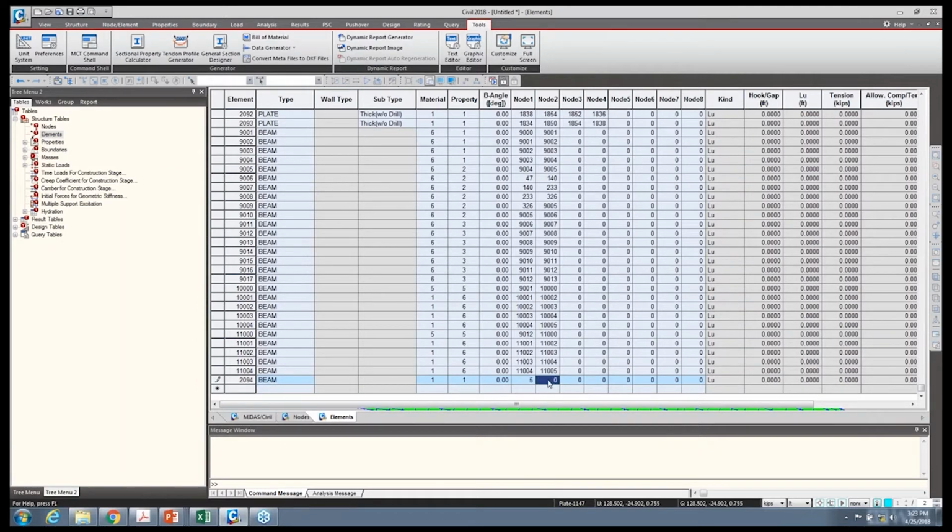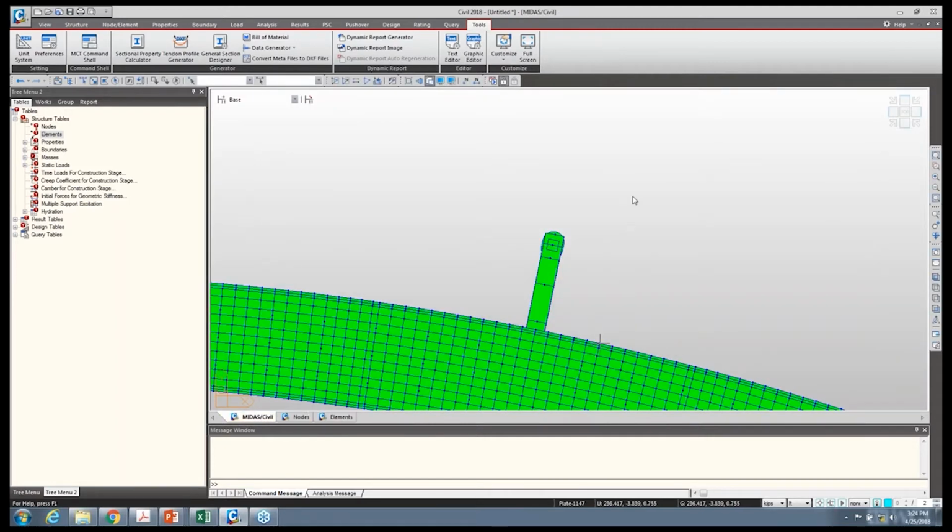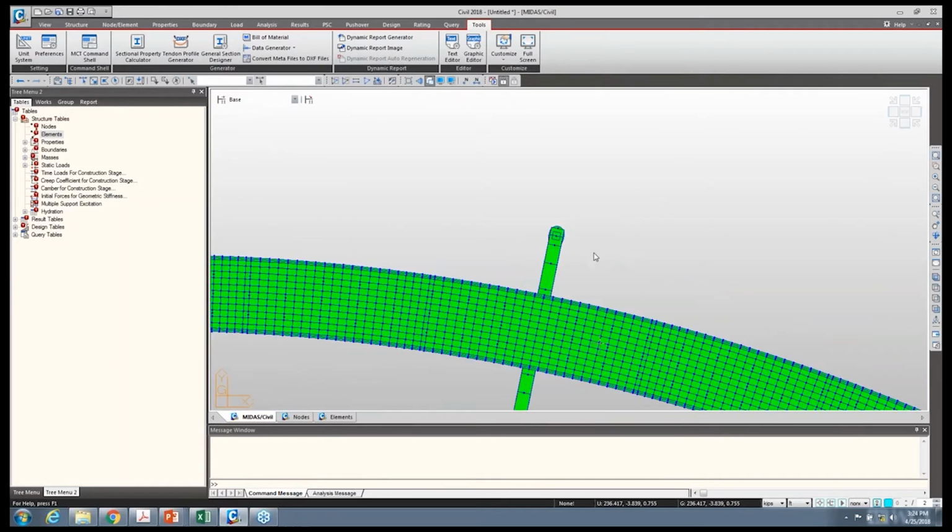It's important for a situation like this, for our structure here, we created this and we supported it on disc bearings. And so they're very, very rigid. So because of that lack of compressibility, I'm not going to model them as elastomeric bearing pads or elastic links. So I'm just going to use the rigid link command. And so I'm going to connect these two members on both sides with rigid links.